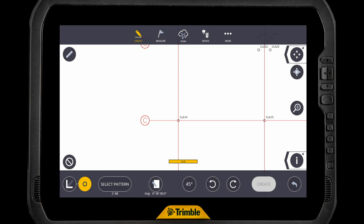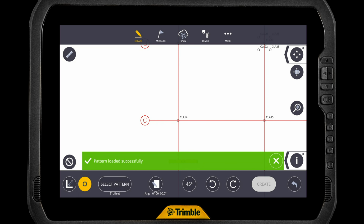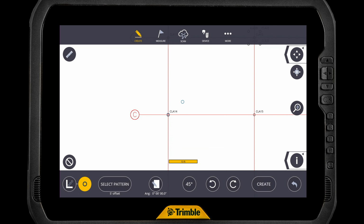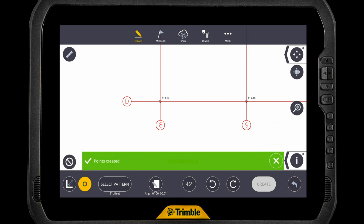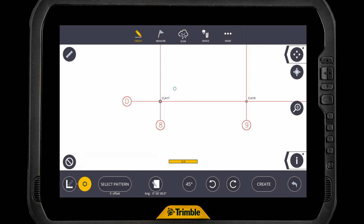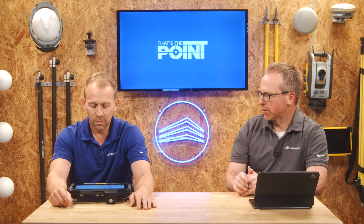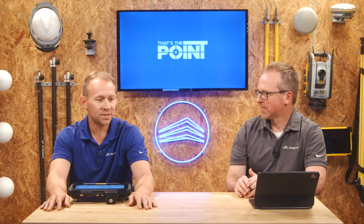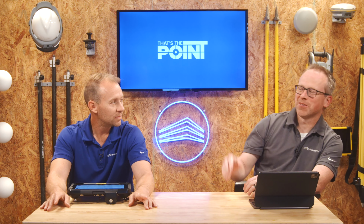So actually if we go to select pattern, I had created one that's a 5 foot offset. So this is 5 feet east, 5 foot north of center. So when I load that one, you'll see now I can just go here. Oh, wow. Create, and as many as I want to. And you're creating all your 5 foot north and east offsets every single time you tap. Then you can set up your whole grid like that. Yeah, much faster and easier than doing it manually like we've done before. That's a pro tip, man. Yeah. That's why we have you on.